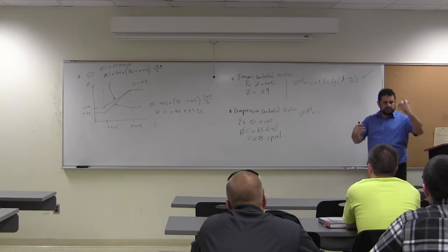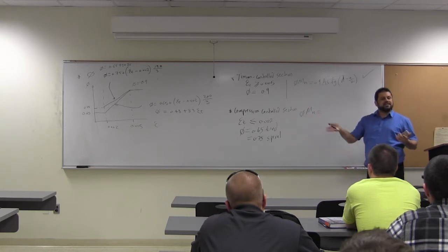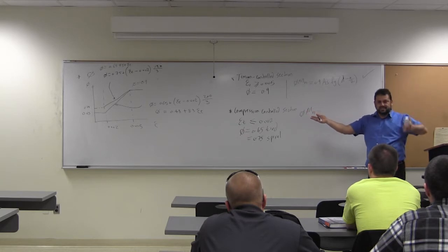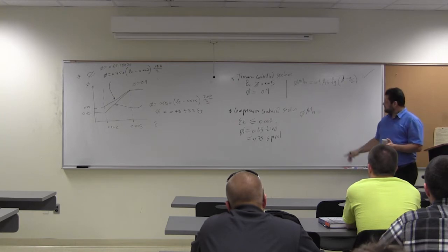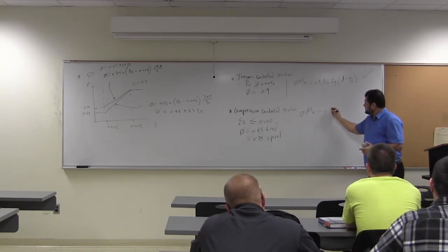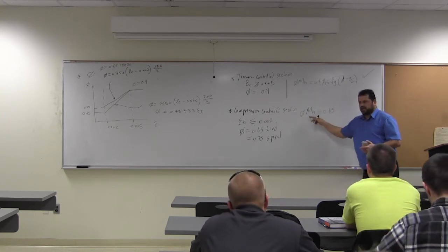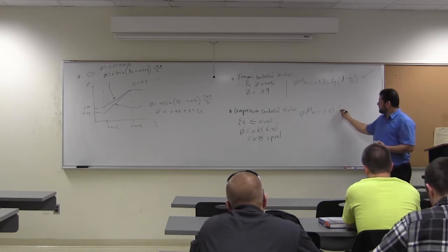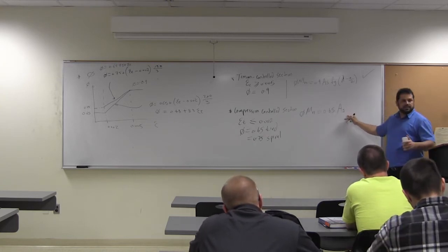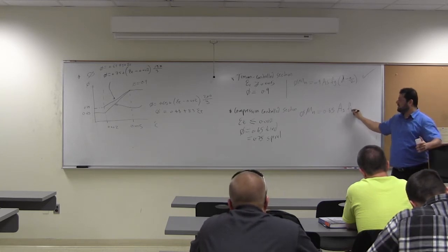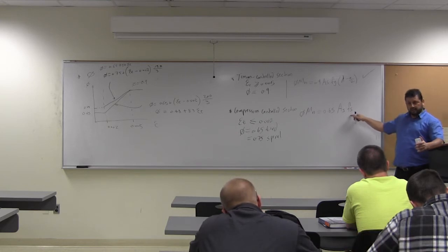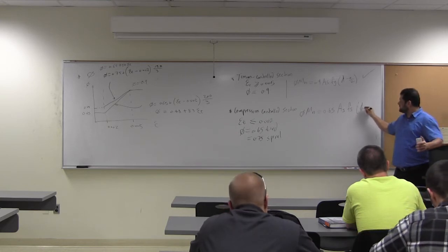When we have an interaction between axial and bending, what's happening? If you have the case of pure bending, that's beam. If you have a case of pure axial, that's column. In between, there's an interaction. What is this? You say, okay, 0.65. If it's tied, it's 0.65. What else? As. What else here? Fs? Of course. It's less than Fy. As, Fs, D minus a over 2.